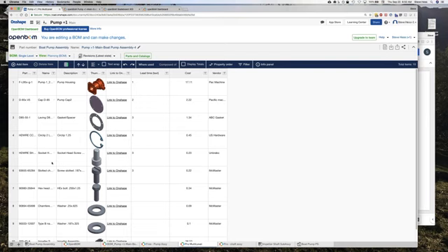So you don't have to put all columns from the bill of materials in OpenBOM into the Onshape drawing, but you can define that, for example, three of the columns from this BOM will be placed in the Onshape drawing. So that's the function of the custom bill of materials. It's not available in imported BOMs. It's only available in a custom bill of materials.